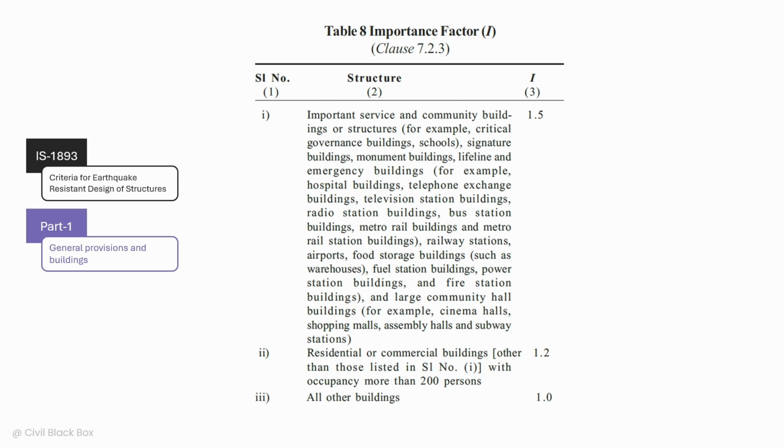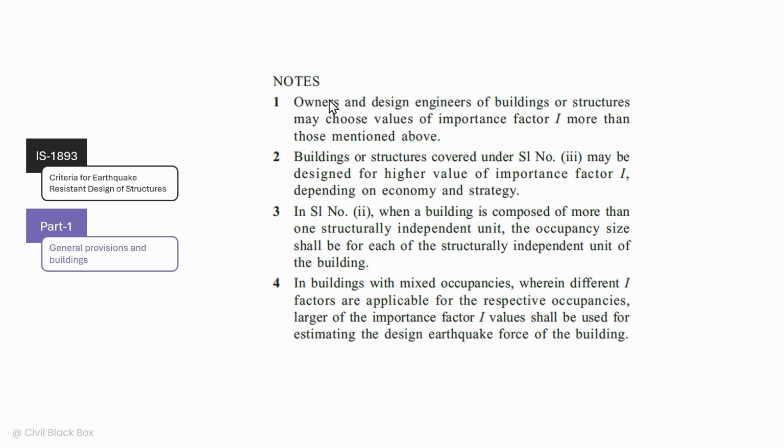Now, in continuation to this, we have a few notes also given, which say that the owners and design engineers may choose a value of importance factor more than those mentioned. Just remember that it has to always be more and never less. So you as a design engineer will have the opportunity of taking an importance factor more than that mentioned, but you have to do so diligently. And we'll talk about where these values are taken higher also. So this is with respect to part 1.